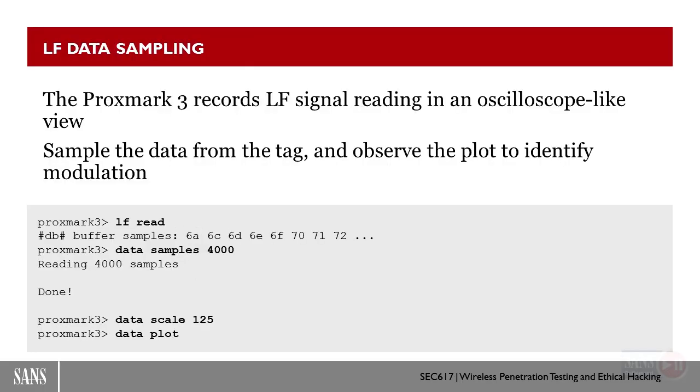We can do some data sampling based on reads from the cards. We now know that it's low frequency, so let's attempt to read the card over and over again and see what the plotted waveform looks like over multiple reads. We can do that with the Proxmark, have it store the data, which we can then analyze offline to examine the waveform.